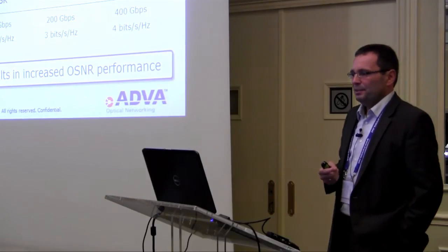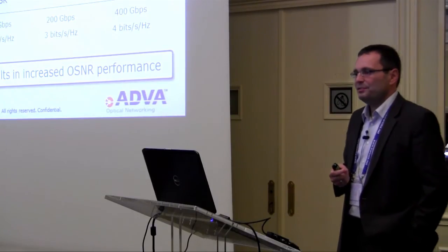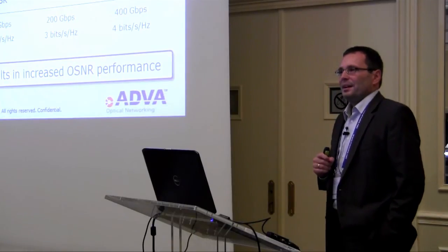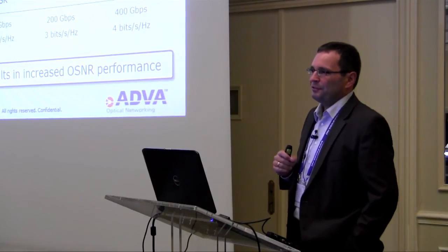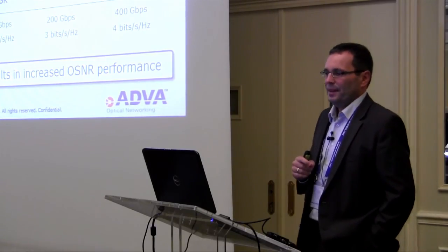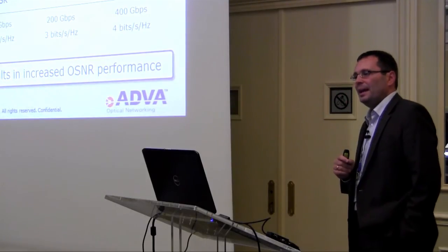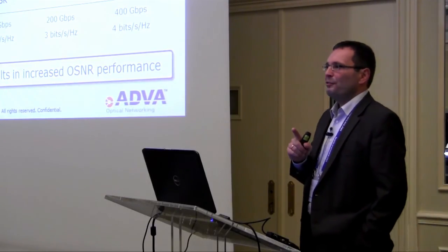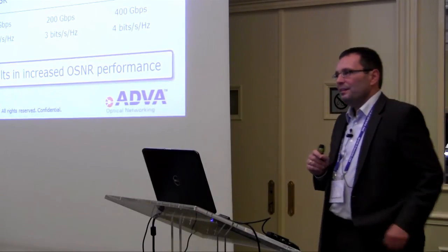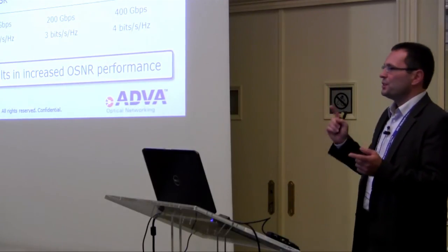We can do a bit better if we use BPSK, which means binary phase shift keying. So it's just 2 symbols there. It's not a lot of gain in terms of capacity, because it's still just 2 symbols, like in the on-off keying model. But those 2 symbols are now much further away than in on-off keying. What does it mean? The further those symbols are away from each other, the more noise I can have and still recover the signal.